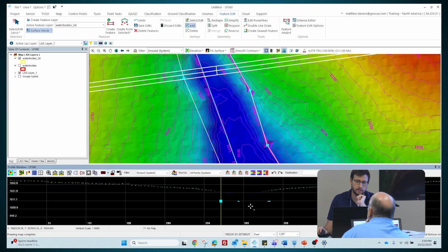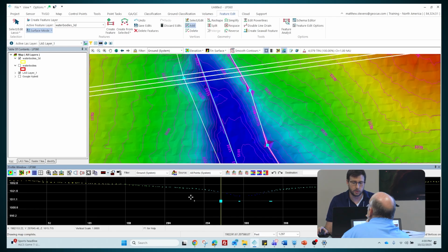I think something we probably need to improve is that if I click on the zoom, it's going to blow away my edit session. I've already created the feature now, so I'll be fine. But if you're making a brand new feature and you hadn't already finished creating it, it's going to blow away the work you've done. So the improvement we need to make is the ability to zoom in and out a little bit easier while you're digitizing. Let me just see if I can force it. Yeah, if you hold down Shift and use your scroll wheel, you can zoom forwards and backwards as well.